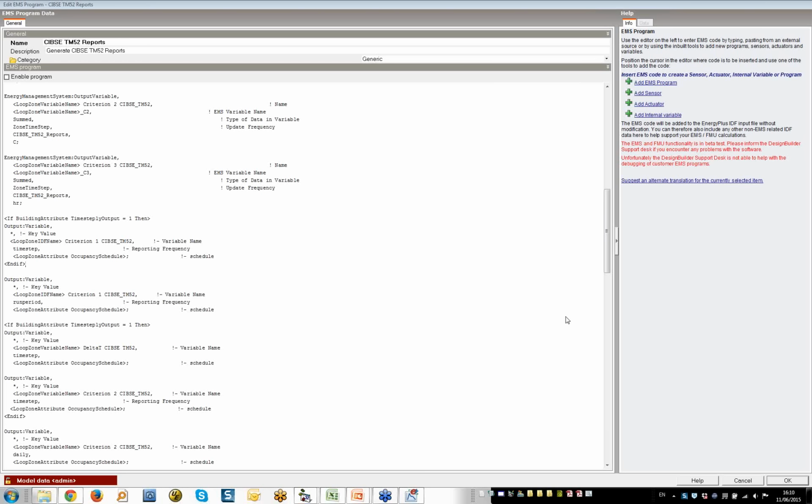And you can feed that DHW with a boiler. You can use a boiler to heat it. You can use an air source heat pump to heat it. And of course, you can store the water in a tank. And of course, you can also provide heat from a solar hot water system. You'll need to use the detailed HVAC mechanism to access these domestic hot water systems with storage.